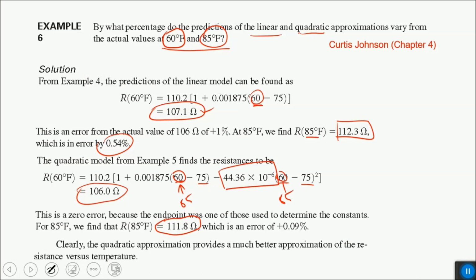So what does all this exercise mean for you in your signal conditioning circuit designs and your temperature measurement applications? If you are using RTDs as your temperature sensing devices in your design, you are getting some value of resistance and you have to find the temperature, and you will use either of these formulae, quadratic or linear.